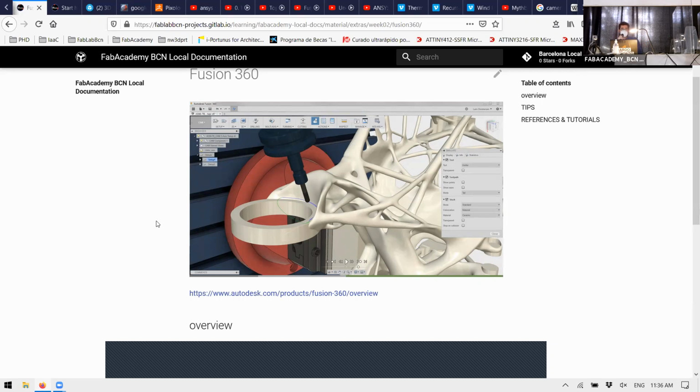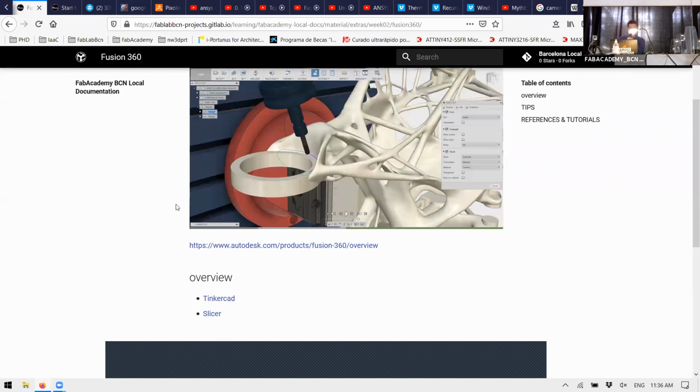You create a circle or a sphere or a basic three-dimensional primitive, and by combining and modifying them, you create your teddy bear, for example. In general, you try to start with a NURBS because it's way easier to modify than a mesh.